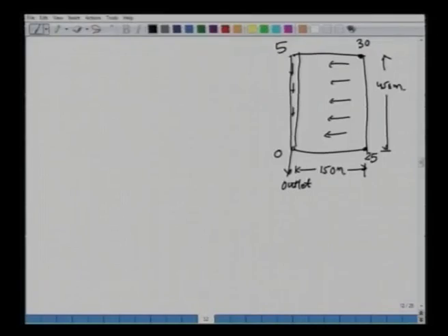So, now we have these 4 points on this rectangle at which we have marked the travel times. How can we draw the isochrones at 5-minute interval? Well, we can do linear interpolation. Using the linear interpolation concept, we can divide it into 5 parts, this one and this one, 5 parts. Now, what will be the time of travel from here?